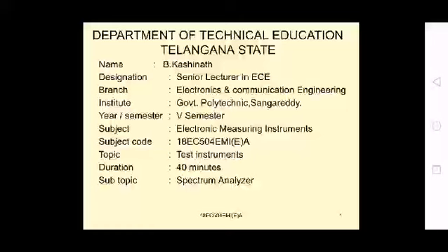The rejection amplifier consists of three parts. First is the pre-amplifier, which amplifies the signal from the impedance converter to a certain level. Then the Wien bridge section of the rejection amplifier acts like a notch filter, which is on resonance at your fundamental frequency, so that frequency will be suppressed, and all the harmonics will be passed through the rejection amplifier. That will be amplified by the post amplifier. Then it is given to the post attenuator section, which attenuates the signal, such that all the harmonic signals are given to the metering circuit.